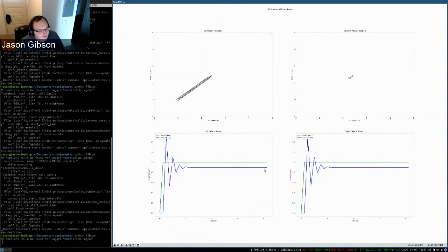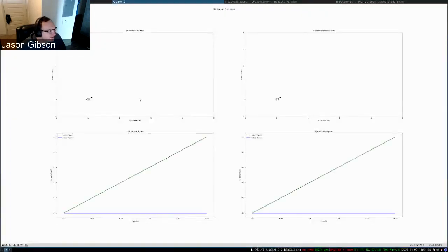But we can sit here and play with this P and play with the D forever to try to reach exactly that point and find the exact P that's going to correspond to it. Because remember, it's just a P multiplied by the error. So whatever this error is, I have to find a P that works here, but you can see that we overshoot even more than we did before. So really what you want to do is increase I, although increasing P is honestly not the worst thing you could do here.